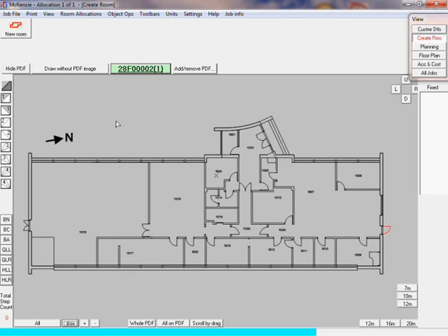The scale has now been set and the guide green has turned to a pastel green to show that this has been done. If your organisation works in feet and inches, then we would be able to set the units to imperial, but for this video we will be using metric. We now want to see just the room that we wish to trace around. So again, we will use the box function to zoom in on this part of the PDF.